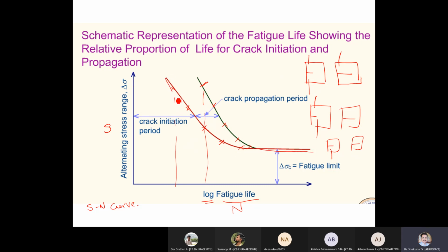Now you plot the graph. So what does this difference show? This difference shows same material, same geometry, same load, but this many cycles are required for this particular load to produce this much crack length. This is the time. Very important graph this is.